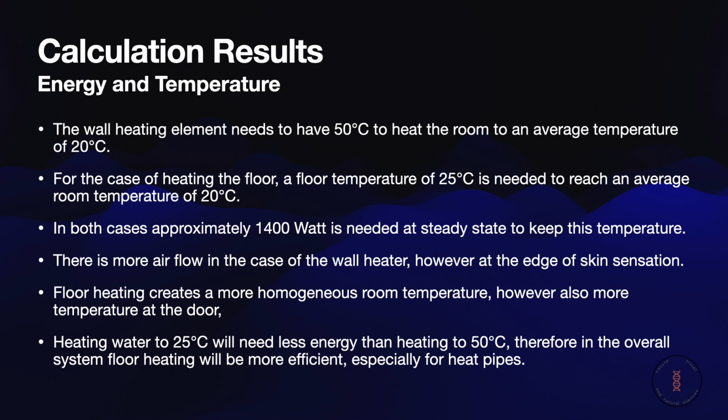The simulation yielded three key findings. Temperature requirements. To maintain a mean room temperature of 20 degrees Celsius, the radiator required a flow temperature of 50 degrees Celsius, whereas the underfloor system only required 25 degrees Celsius.